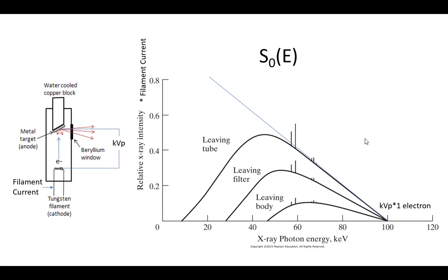Because it's far enough out that the difference between that conduction band and infinity is really small. So as we raise that temperature, it's going to promote it. Well, therefore, the hotter this is, the more electrons I get. Right? It's actually pretty linear in this region, so that's pretty nice. Temperature proportional to electrons. Well, temperature is also proportional to how much current you're running through this. More current, more temperature, more electrons sitting around to accelerate. Therefore, the available electrons to produce X-rays is proportional to the current in the filament.